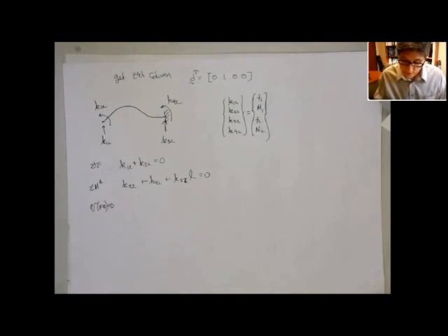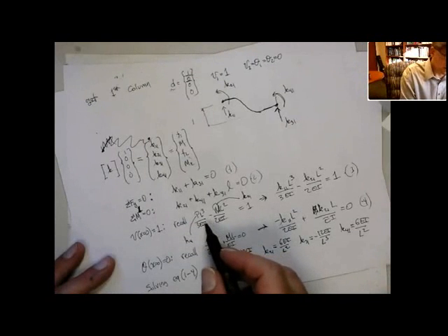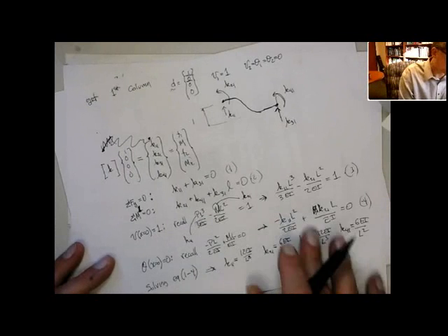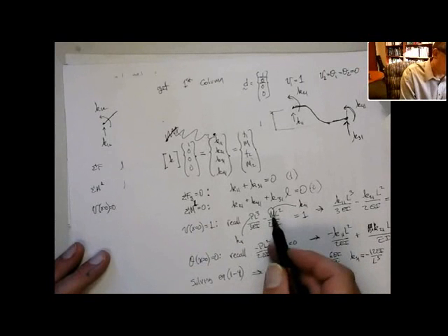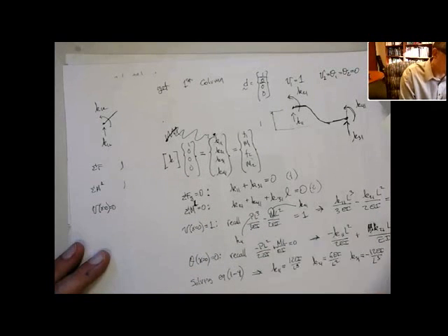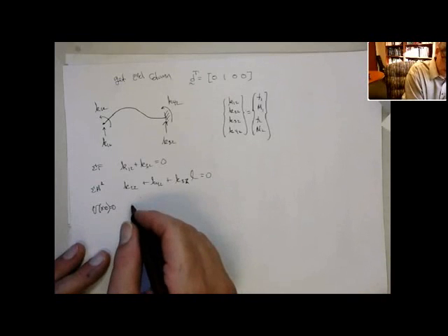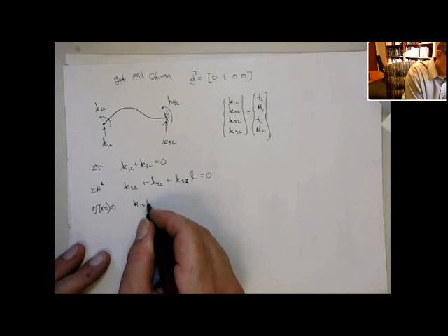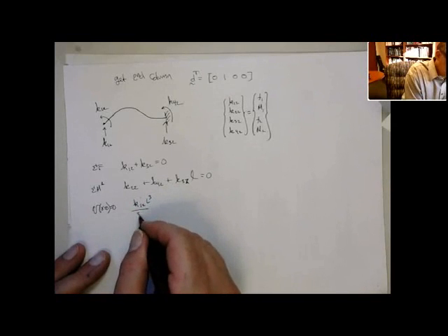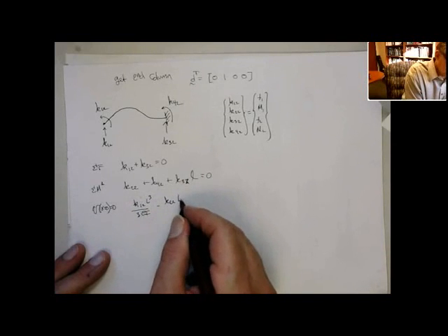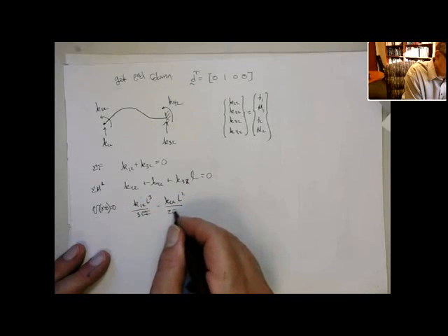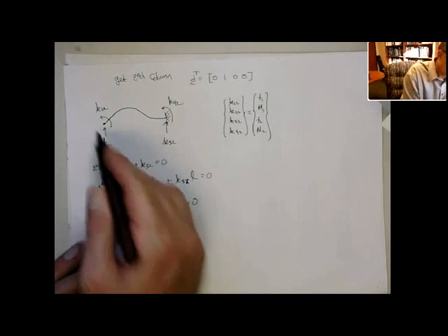Going back to the equations we had before, we're going to use this equation, but we're going to put in different values for P and M. In this case, P is going to be K1,2, and M is going to be K2,2. So we get K1,2 times L cubed over 3EI minus K2,2 times L squared over 2EI has to go to 0 because the deflection is 0.